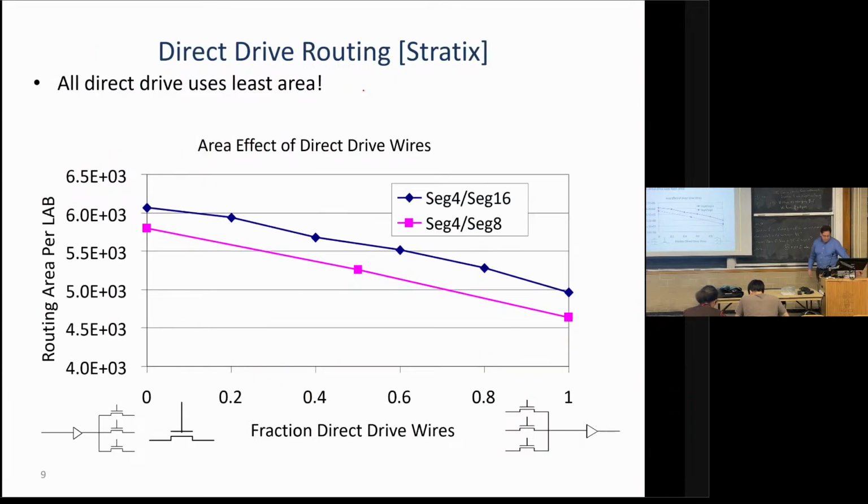Okay, so then this puts together, what about area, right? We don't really directly care that much about channel width. We care about area. Channel width affects area. If we need more routing wires and more routing drivers, that's going to tend to increase area, but it's not the only thing.